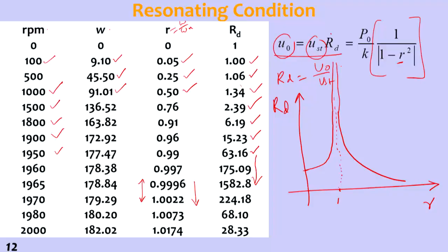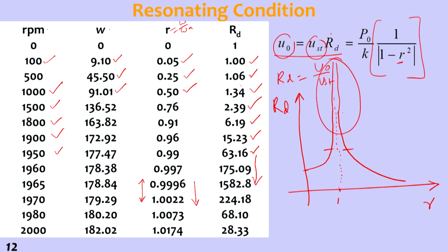So this tells us the importance of damping being present in the vibrating system, especially near resonating conditions. Here it is within the limits of deflection, but when it is nearing the resonating condition, the deflections are very high and the system may break. So damping is very important to be included in systems where the frequency of vibration is very close to the natural frequency of the system.